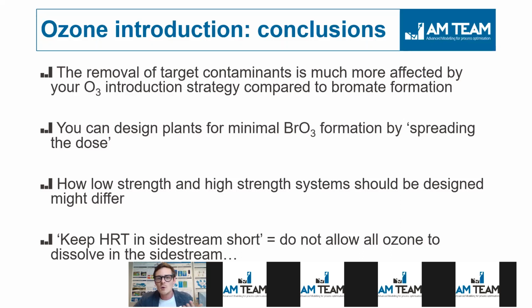In fact, there is also a lot to do, as we practitioners know, with side stream versus bubble column. Yes, there are differences in costs, in maintenance, pros and cons for each, but there are potentially differences in bromate formation as well. I'm not saying that side stream is inherently leading to higher bromate formation. There are side stream systems out there that produce very limited bromate. But if you talk about keeping the HRT in the side stream short, because that's the general guidance, if that is too long, your bromate goes up very, very fast.